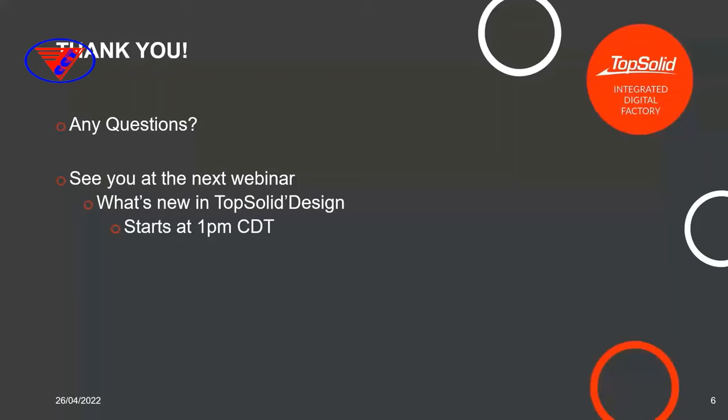I see another one. Does free shape remove the existing holes? It removes the existing holes, it heals them out, and replaces them with TopSolid drillings. So at the end, if the hole is still there, it's still in the same location, it gives you the ability to identify it. So for example, let's say you import a part made in SolidWorks. It comes in, it's dumb data, right?